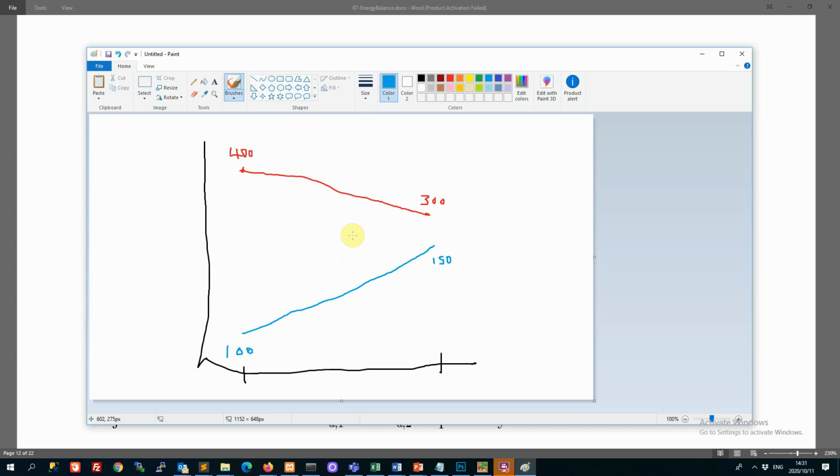So there has been heat exchange across here. However, at all stages, you can see the jacket was always at a higher temperature than the reactor. So even though its temperature dropped, it never dropped so low that it was meeting the same temperature as the reactor. So it never got the chance to equilibrate in terms of temperature. So there was always heat transfer, although likely the heat transfer rate was lower towards the end than at the beginning. So that's what can happen in your heat transfer.